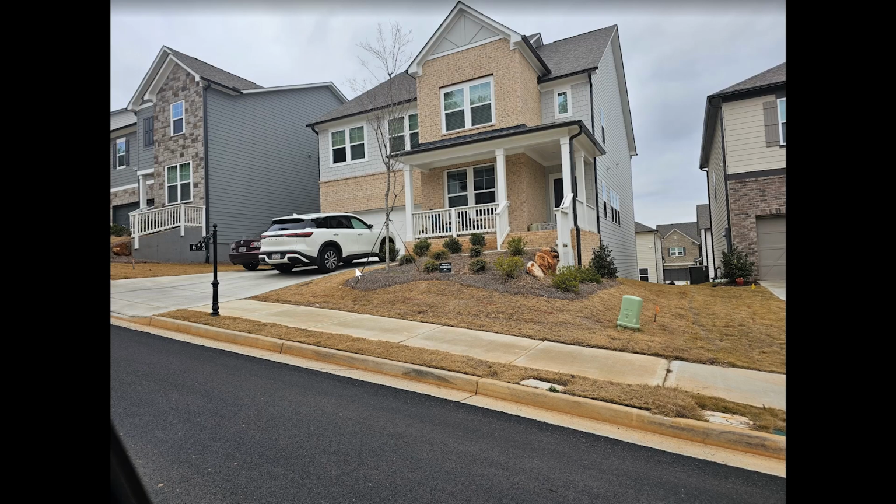And I think it's one more example. This is a basement lot. I think all three of these are basement lots, but this is a pretty extreme road. I think this is at like a 15% grade, so it's pretty steep. And so we'll have a lot of elevation change or step down between the lots, the house finished floor elevations and the garage elevations. So I'm just sketching in here how the flow of water will look with this, and kind of sketching in what the contours are going to look like.